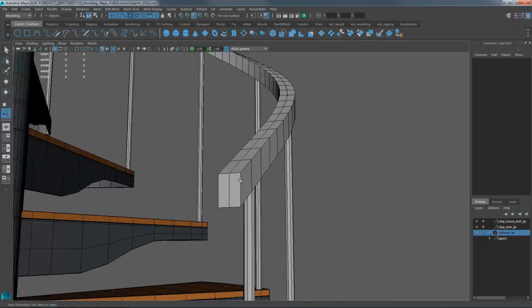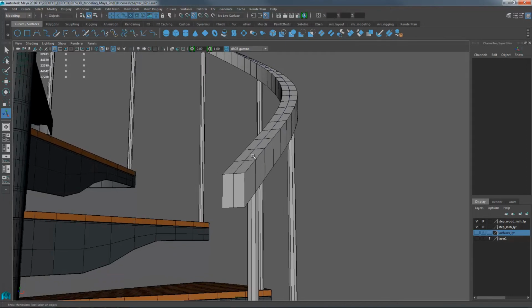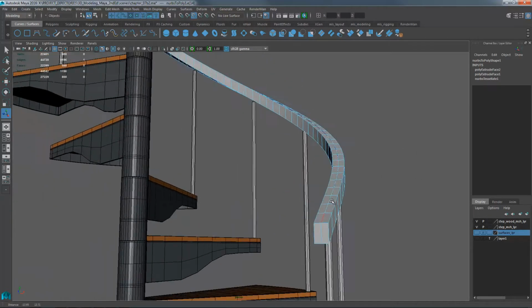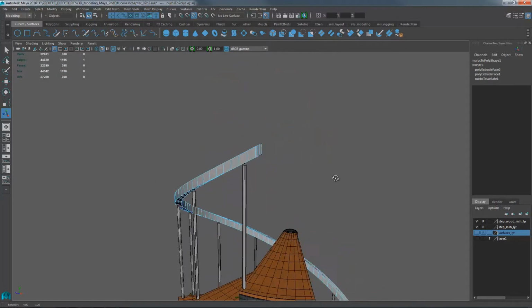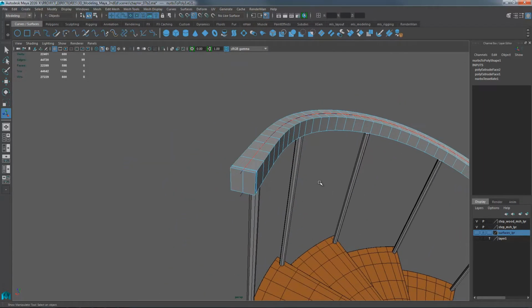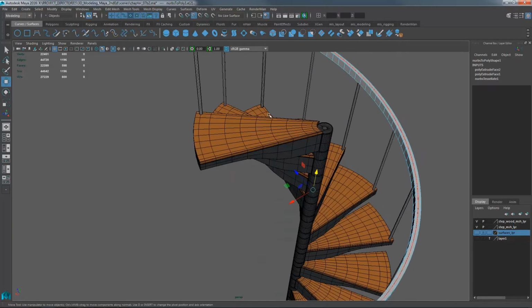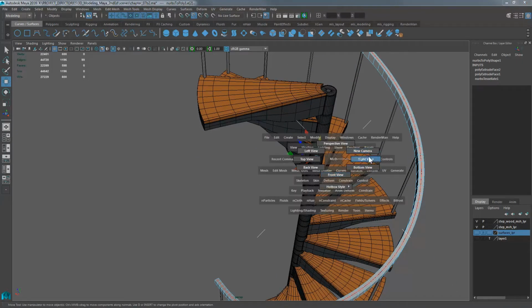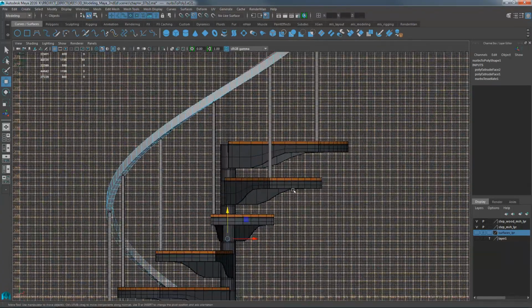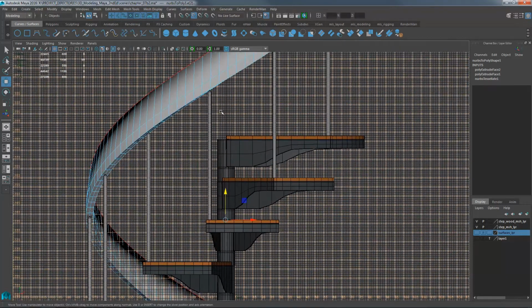And as for the square bottom but round top profile we talked about, that could be as simple as taking this one edge loop and moving it up, but I think I need at least 2. Let's get 2. Or, no, let's use this 1 and then use edge flow. Maybe edge flow to help do the rest. And then translate that edge straight up. So let's go to the front view, frame it, and translate that up. Turn off snapping.